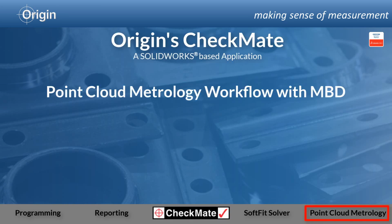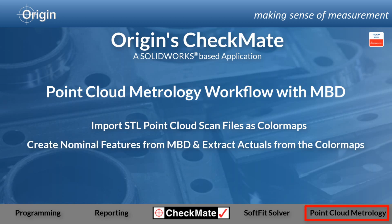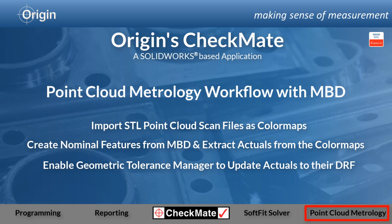This video is going to review the workflow of importing 6 STL point cloud scan files as color maps, creating nominal features from SOLIDWORKS MBD and extracting actuals from those color maps, enabling the Geometric Tolerance Manager to update the actuals to their datum reference frames, and then generating an Excel PPAP report.